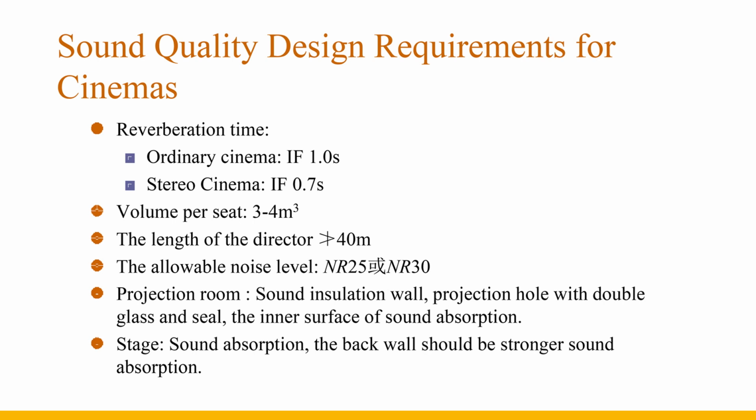The length of the hall should not exceed 40 meters, and any longer will make the audience in the back row feel like the sound is behind the screen and the sound level in the front row too loud. The audible noise level of the auditorium is higher than that of the theater, which is NR25 or NR30. Sound insulation should be done between the projection room and the auditorium.